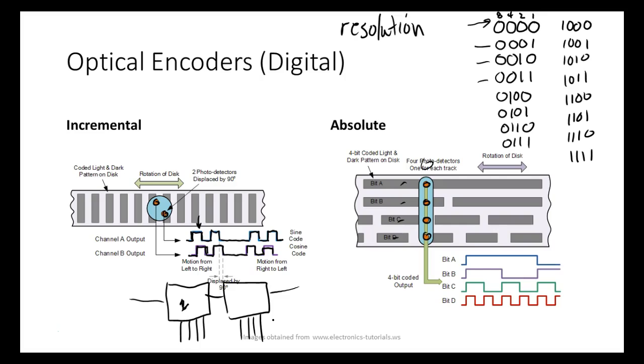What's the disadvantage of this, the guys up there? So I turn my machine off. As soon as I turn my machine off, these electronic counters are going to lose their count and start all over. I turn it back on, the counters say zero, but my piece of equipment is out here somewhere. So what we have to do, one of two things, what the robots do, is they keep these counters, they have batteries inside of them.